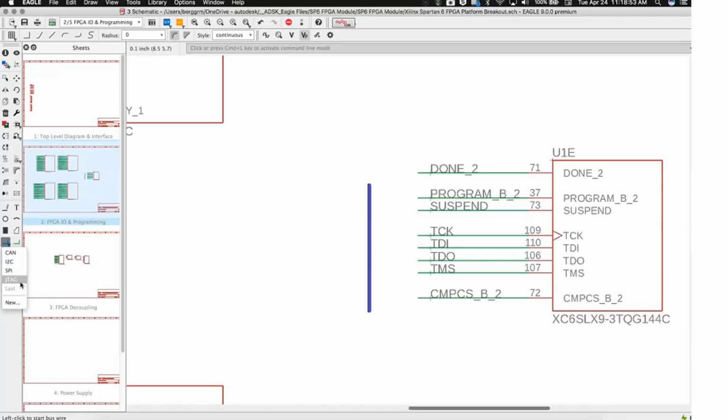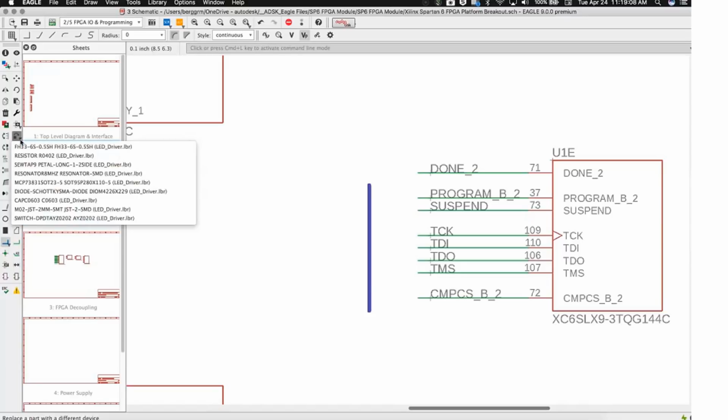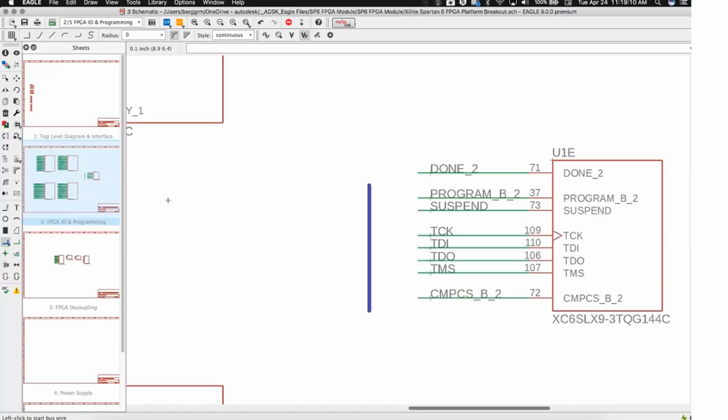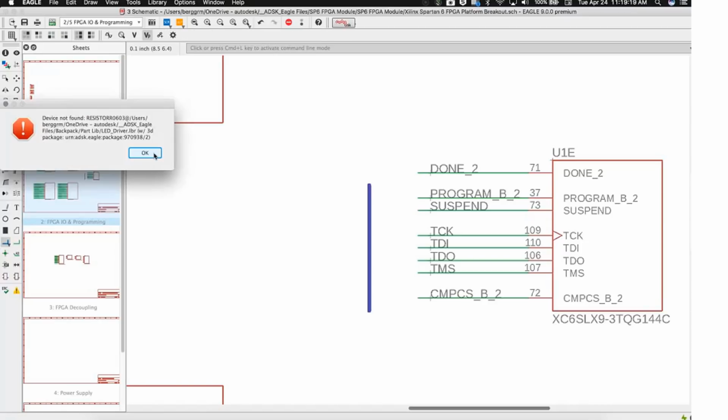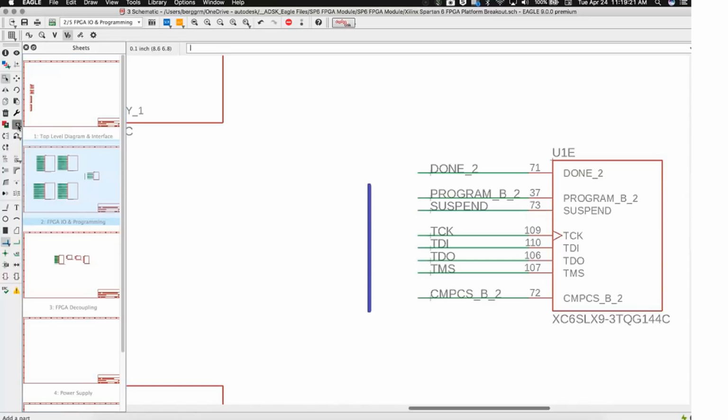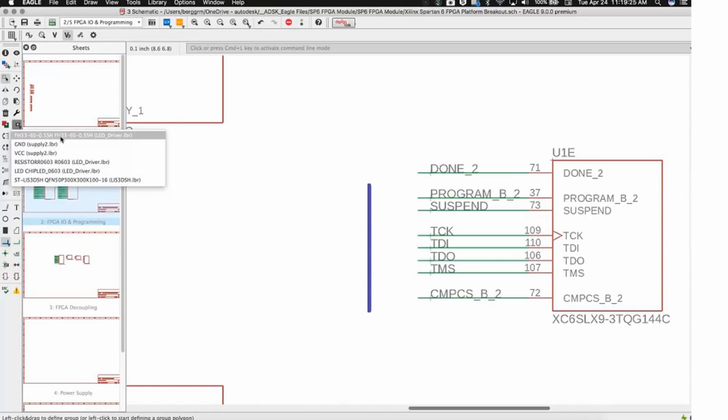So one of the things that we added in Eagle version 9 was the ability to create what we call persistent buses. And for those of you that don't know, any of these menu commands over here, toolbar items over here, which have a little downward pointing arrow next to them, if you just click and hold on them, they'll actually expose a whole bunch of stuff underneath them. And this is not anything new to Eagle. But you can see here that I can pick a set of recently placed components and just drop a new component in there. In this case, that library wasn't set up anymore. But I can drop a new component into my design just by virtue of placing a part that was a legacy part here. So as you start to place things, you'll accumulate this list of recently used items.